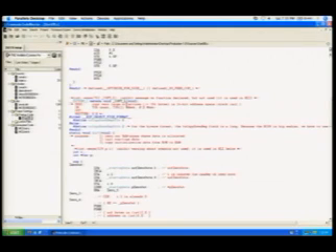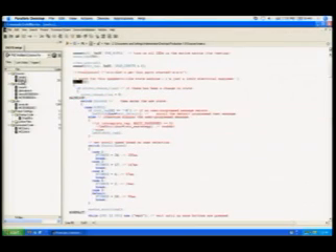Once you get into main, basically all you do is you loop around. What he's done here is he's implemented a state machine using a while loop and a current state. He's got all his interrupts for the keyboard handled as interrupts rather than polling the status, so he can sit in infinite loops while waiting for more input to occur. When it does occur, he just jumps over to that and then jumps back. It's very simple code, and it's very easy to modify if you know what it's doing.